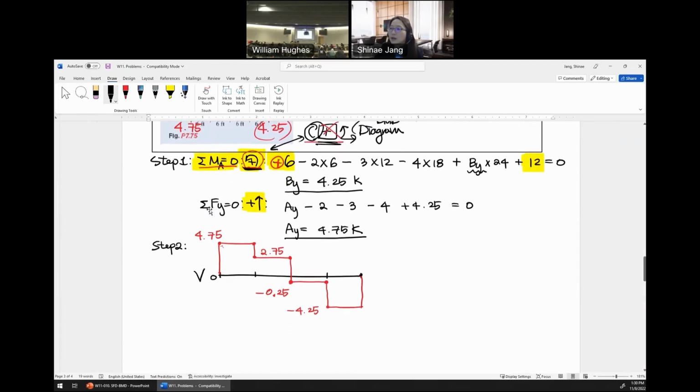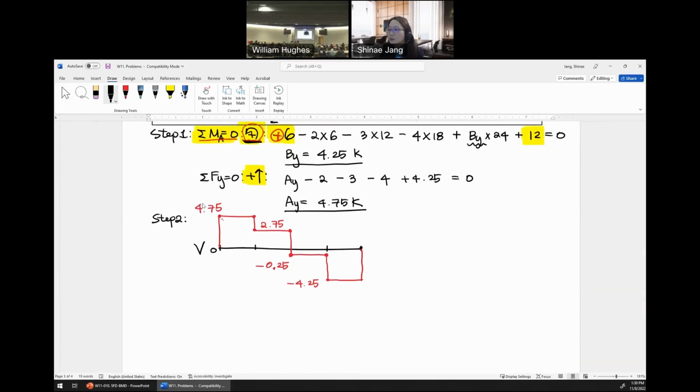Okay, and now the bending moment diagram, right? So for the bending moment diagram here, we have moment, and then mid span, quarter span. And then we'll use the graphical method. From the shear force to bending moment, it's integration, right? So the area under the shear force diagram is the change in the bending moment. So then we need to find the area under these rectangles. And that is really simple, so I'll give you the numbers. The first area is 28.5.